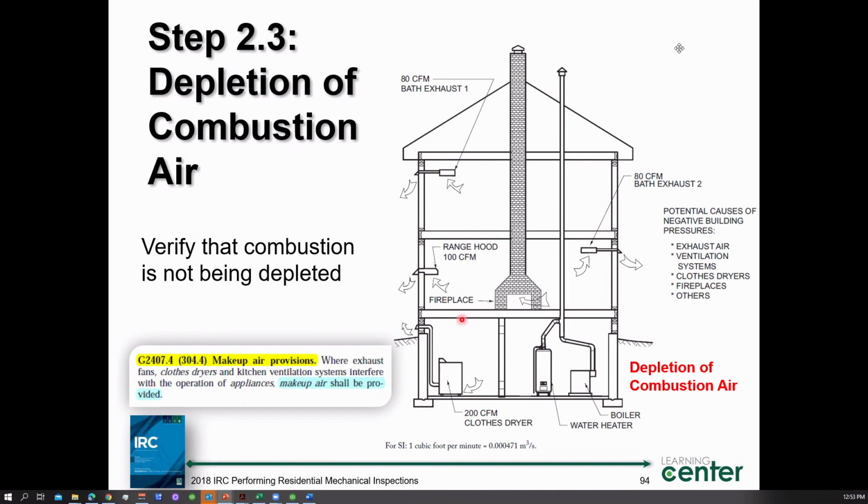Where am I getting the makeup air? I got no combustion air. I got no makeup air. I've got nothing. What's happening to the flames? What's happening to the combustion process in my water heater and my boiler with the draft hood? You know what's happening? The flames are starting to maybe lick out of the door here.